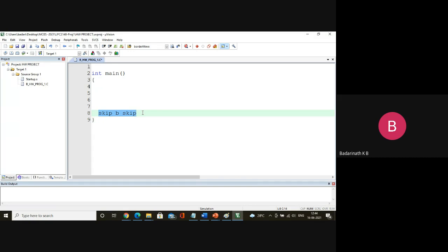So you have to repeatedly execute the last statement, so that it stays within the code execution. The microcontroller should not go to memory areas where the code is not present, so you should not execute undefined code. So what do we do in C for the same thing? I'll repeat that here by using while(1). I can write it like this, or directly like this. Now this will be the last statement.